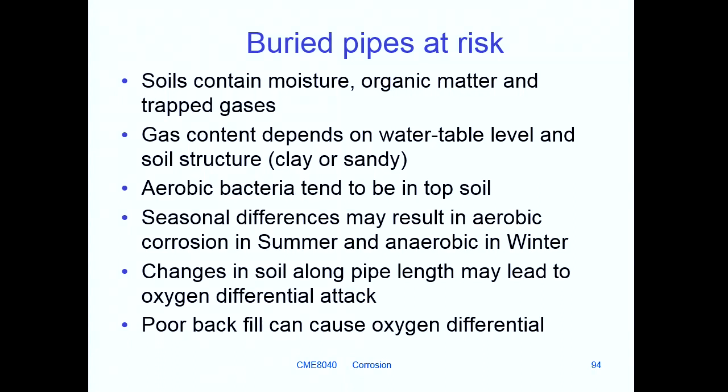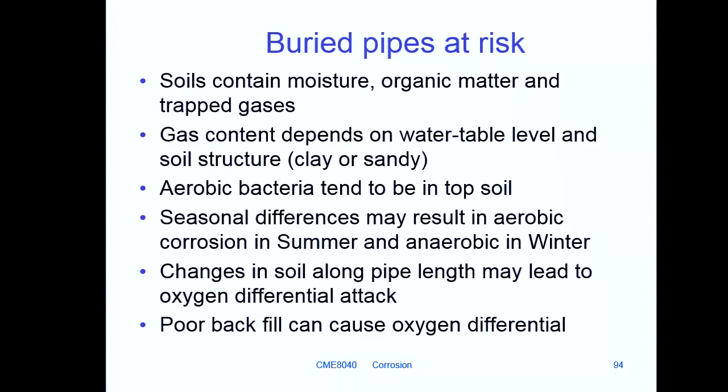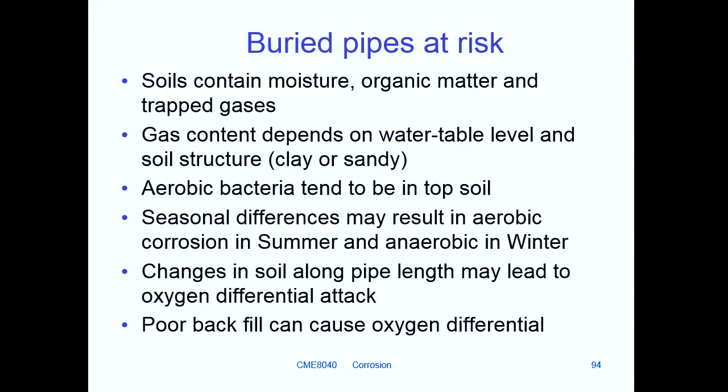That's your water table, and that water table height changes depending on whether it's summer or winter, and it also depends on whether the soil is sandy or clay. So in a sandy soil, the water table may be in the order of 3 meters or so in depth from the topsoil to the water table. In a sandy condition, the water table is quite low, and also in hot environments. In a clay soil, the water table might be quite high.